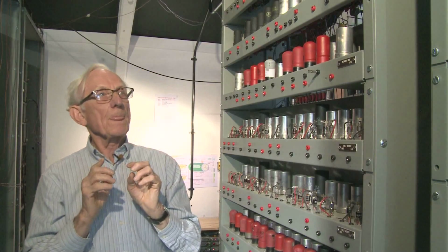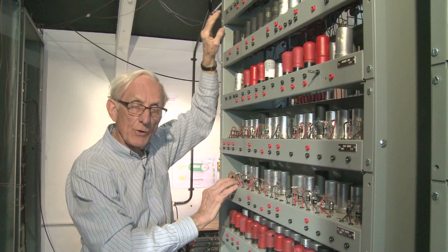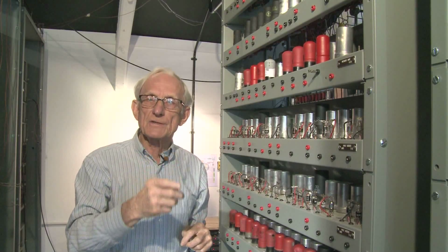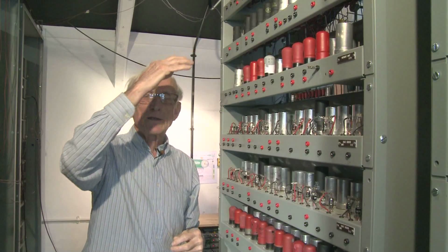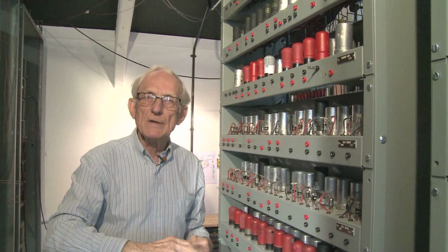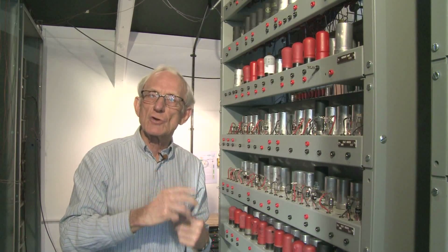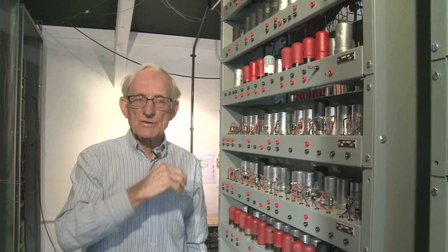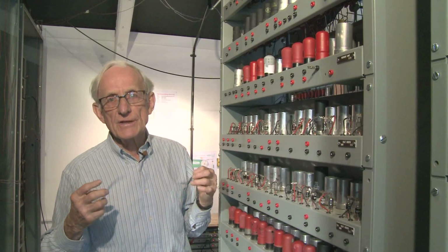That's the counter tank. Now, similarly, there's a short tank with its own half adder, and that adds 1 into the bottom of its count every time an instruction is executed. So that tank is keeping count of instructions within a program. It's what in modern terms we'd call a program counter. It's the sequence control tank. And the number in that tank is telling the rest of the machine, this is the address of the instruction